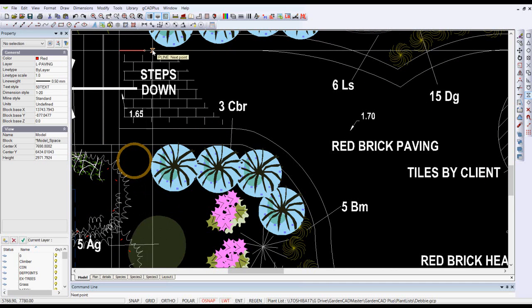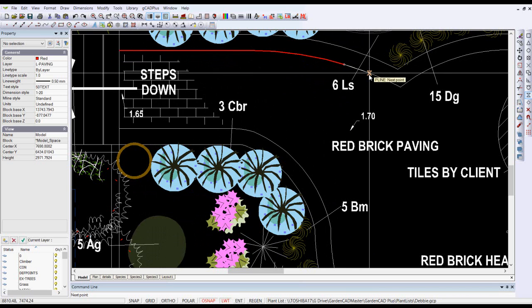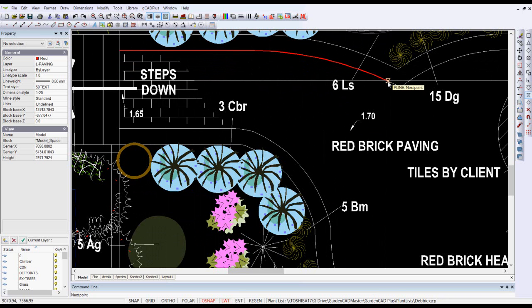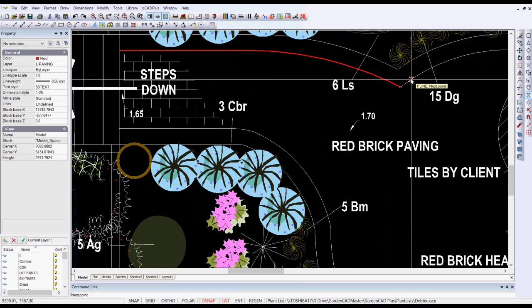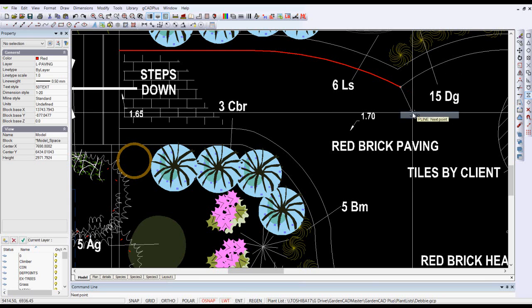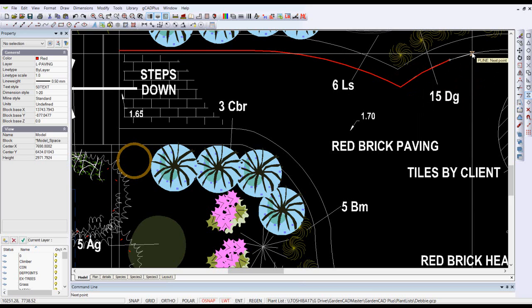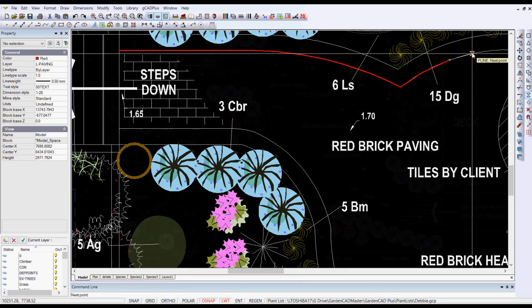And then as I move away, you will see my drawing color is red, and I've deliberately set the line weight to be quite heavy. Can you see that I can move around and trace around the edge of this shape really quite easily? Whoops. Now I can right click and undo that and then locate back on. So the combination of Object Snap and changing your color and line thickness helps when you're trying to trace over a complex area such as this.